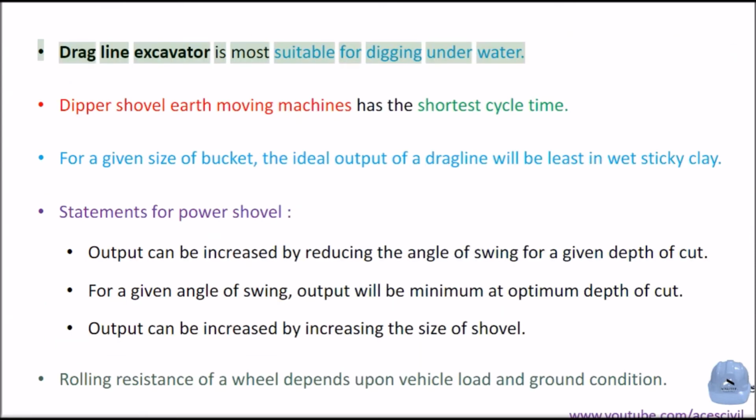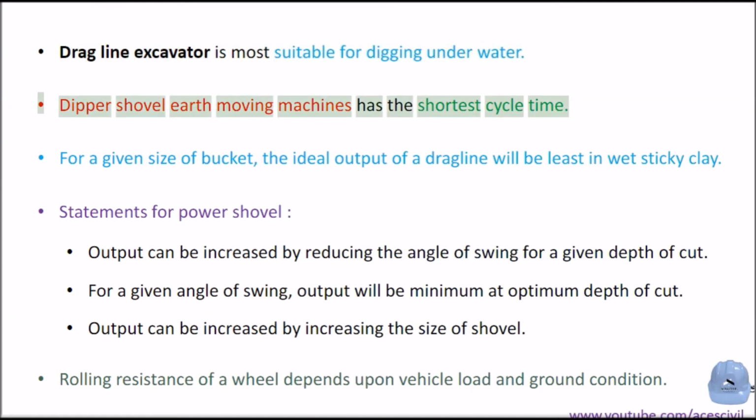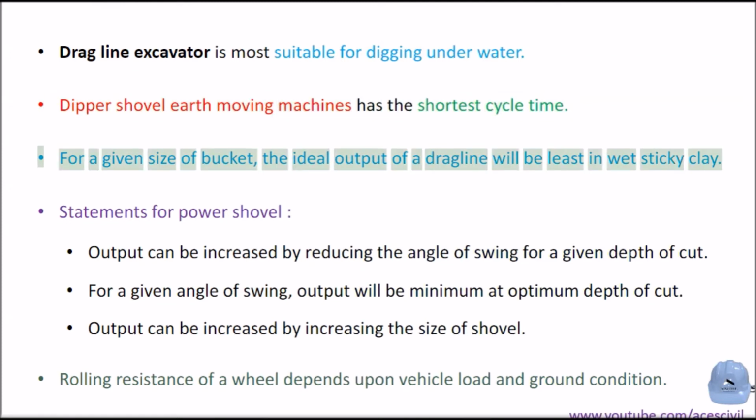Dragline excavator is most suitable for digging underwater. Dipper shovel earth moving machine has the shortest cycle time. For a given size of bucket, the ideal output of a dragline will be least in wet sticky clay.